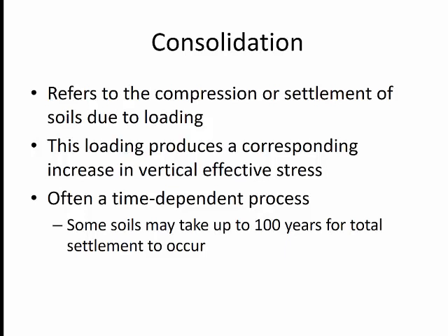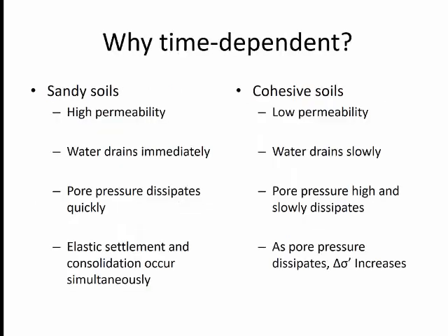This loading produces corresponding vertical effective stress, which, as we've already stated, produces strains. Again, this is a time-dependent process because oftentimes the soil has an attraction to the water that does not allow it to expel or travel through the soil very easily, and sometimes it can take a very, very long time for that settlement to occur. And this experiment allows us to determine how long that does take.